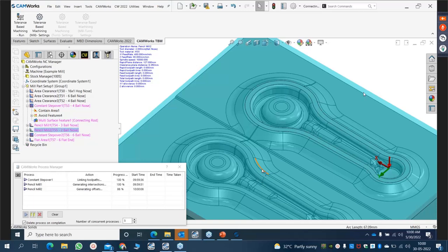So the main cavity area is important. The finish has to be maintained there, but the outside area, there will be material flowing outside, is the flush area. So not much finish is required. We can save some time and generate it separately.